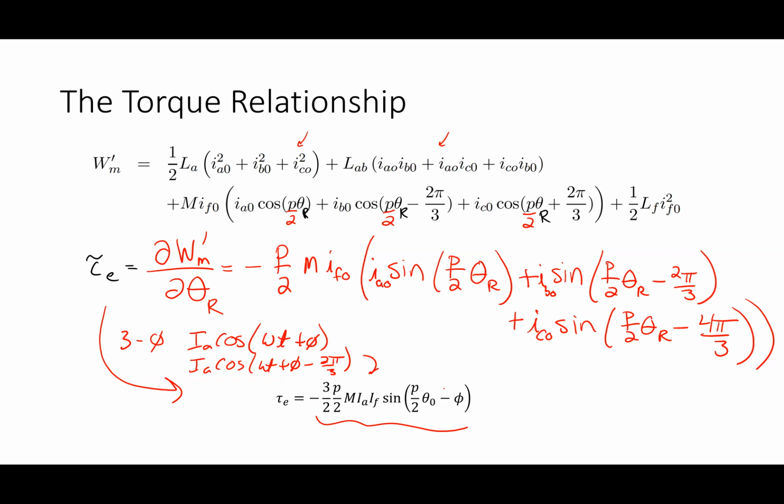If I'm in the motor world, it's the opposite. In the motor world, you apply the torque and the mechanical world slows you down. The generator world, I rotate it, and the currents act to slow it down. And that's phi. What do I call that phi? I'm going to get to a generator picture in a minute where I have some voltage sources and stuff. This is my power factor angle.